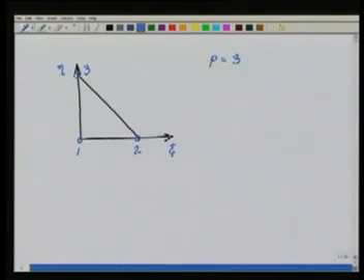So the one-dimensional cubic shape functions correspond, in terms of the definition, to the Lagrangian functions for these 4 equally spaced points on this edge. This point will correspond to the coordinate 1/3, 0, this will correspond to 2/3, 0, and this is 1, 0.